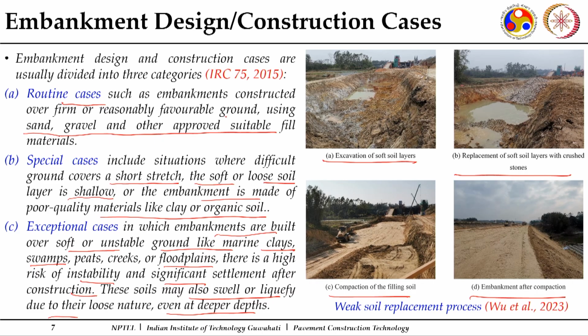So this has to be given due consideration. Even if you are doing embankment construction with a selected material, if these embankments are to be of greater heights, then the land over which the embankment is coming up, if it is very weak, may be a challenging situation. So these factors need to be taken care of when you are making an embankment construction. And what you select for use in embankment construction is another concern, because it should be as per the requirements.